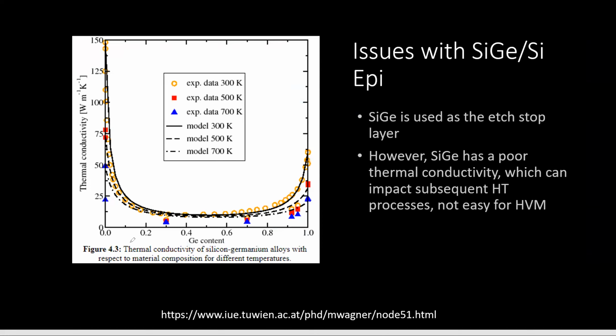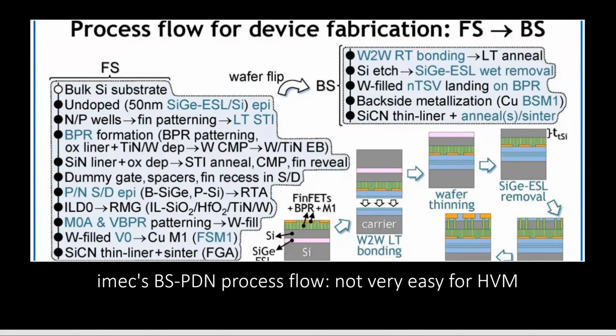And actually, there's good reason for that. By the way, you cannot go over 30% because this is 15 nanometers thick. You cannot have germanium content too high, otherwise it will crack. It will form dislocations. So the germanium content has a strong relationship with how thick you can put it on. It's not an easy thing to do. So you cannot say germanium at 80%.